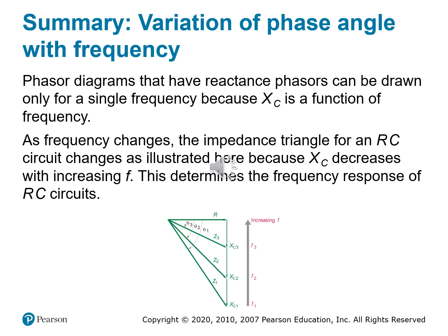And then compare this to inductors. Think back to our RL triangle. Inductive reactance increases with frequency, causing the angle to rise. Capacitors behave in a mirror-image fashion. Another reason why RC and RL circuits often complement each other in filter design.